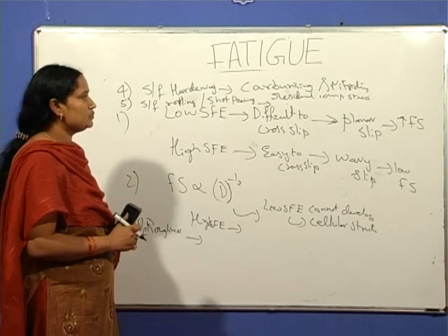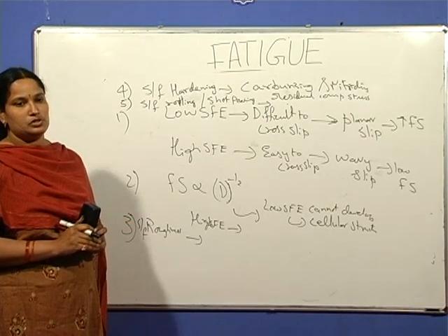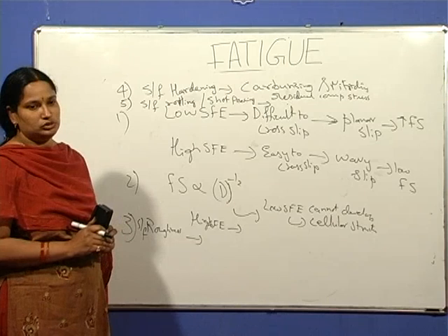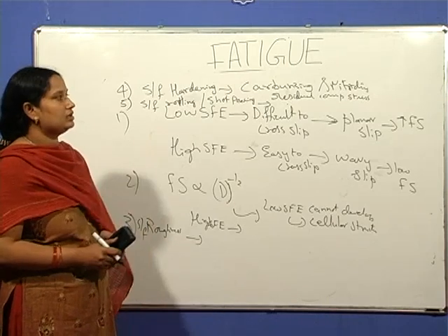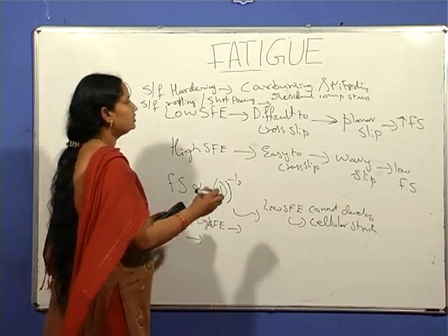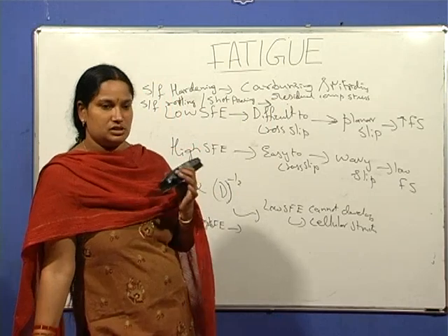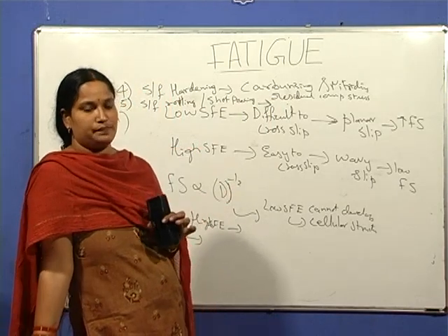So this induces residual compressive stresses on the component. One can measure the amount of this residual compressive stress by testing the residual deformation of these fine shots.